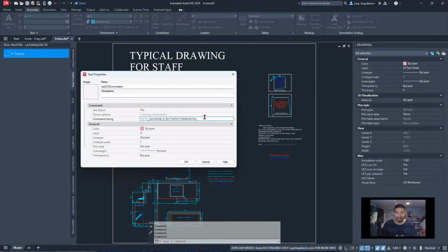But once we select this, what do we want to do with this, right? Well, per the client request, what we need to do is erase these items. So I'm gonna use the erase command, followed by an enter, of course, and then I need to erase our previous selection. So I'm gonna say P and then input 2 times enter. So let's quickly test this first piece of code, to see whether we have any problems, so we can quickly toggle and fix them.